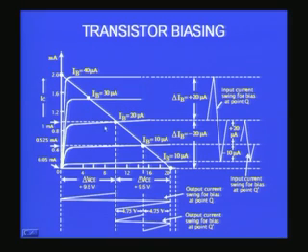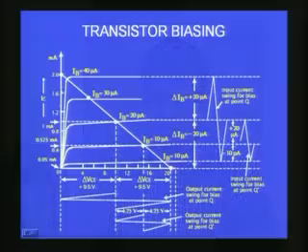So, you find when this base current changes by a very small 10 microampere range, the collector current changes from the operating point 1 milliampere to nearly 1.65 milliamperes to 0.5 milliampere, nearly about 1 milliampere plus or minus 0.5 milliamperes, and therefore when passed through an RC of 10K can give me 0.5 into 10, 5 volts plus or minus 5 volts. So, that is what is shown here.